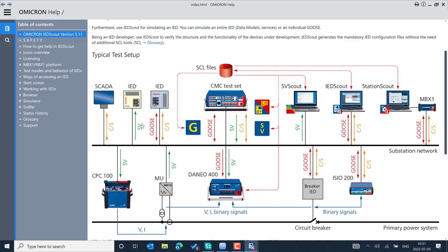Sometimes you also have the metering devices. Basically BCUs send the metering data to the SCADA HMI for monitoring purposes, so those reports can also be captured by IED Scout. Then you can even control the tap position, if you have the dedicated function in the bay control unit, or a separate IED for monitoring the transformer inputs and also the set point control for the tap changer.